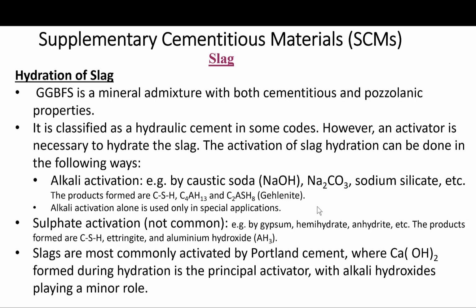So that is the use in the common sense we are familiar with. The slag is used as a mineral admixture, as a replacement of cement, for the various benefits we get from other pozzolanic materials. Yes, it exhibits some cementitious behavior, and those could be used in special applications where an activator is needed. But for the context of this class, the slags are just activated by the Portland cement, and they work as a mineral admixture.